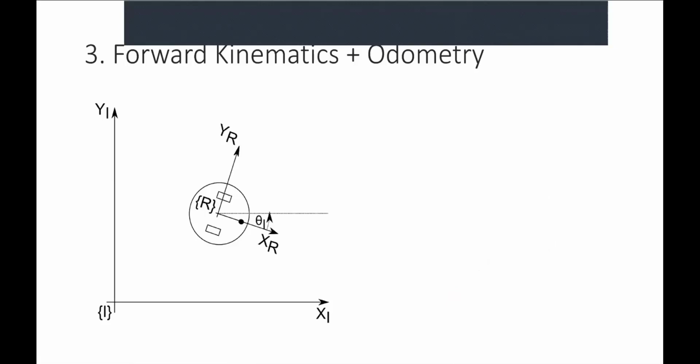So if we wanted to put this in terms of some inertial frame, right? So this set of axes out here, then I just need to relate those local translations and rotations that the robot has made back into this other coordinate frame. And so I can say that the x and the y offset, right, from that last movement is going to be the x component and y component of my robot's motion. So here we have x.I is the x component of my robot's displacement minus the y component of my robot's displacement. So we knew that this one was 0, so we don't have to worry about that. So it's just the x component. So project that x.r vector onto the x-axis for my x displacement, and then my y displacement in the inertial frame is just the y component of that. So we're essentially just attributing portions of x.r to each of my axes using sine and cos here. And because our rotation axis lines up, there's no translation or transform that has to happen there. The rotation that my robot experiences is the same one that I would see in my inertial frame.